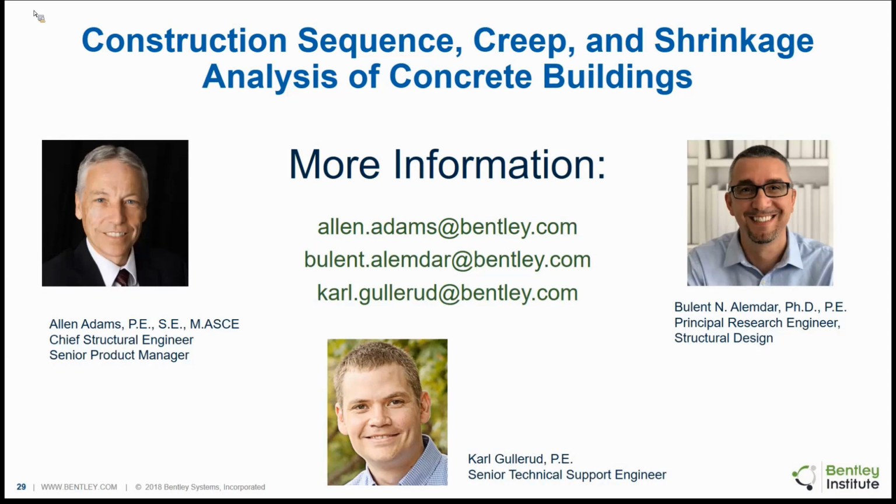Again, if you've modeled the slab as a semi-rigid diaphragm, the program's going to mesh that. Those slabs will be part of the analytical model, and so in stage one, for example, the slab of the first floor will be included in the model because it was modeled as a semi-rigid diaphragm, and the construction stage analysis will impact forces in the slab and how the slab behaves in pushing back on those sloping columns, etc. So yes, that's all taken into account in the analysis.